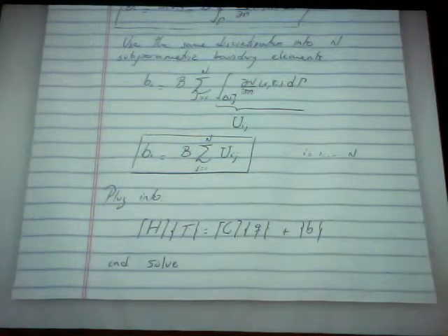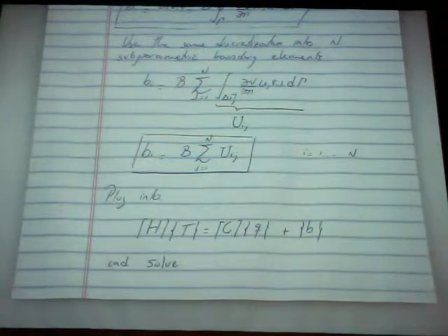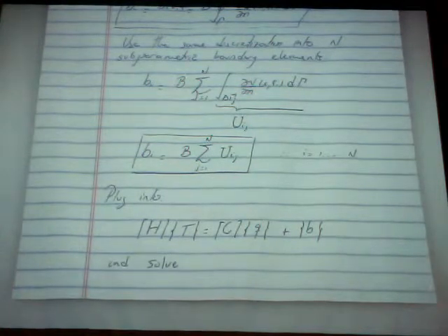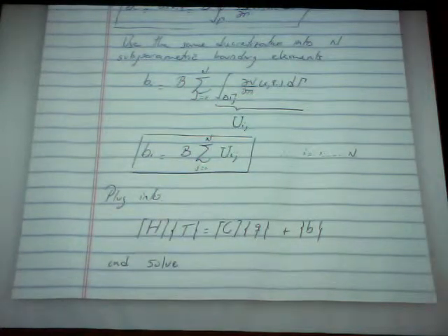Now next Thursday, we're gonna see what we do when the generation is not constant. And that will help us actually cover a much wider range of problems, not only these Poisson-like problems, but other problems in which there's stuff in the equation that we don't know how to handle, and then we can send it over to the right-hand side, treat it as a known quantity, although it's not known, it might be a function of temperature, assume what it is, treat it as a space-dependent generation, solve the problem, and iterate back and forth until we get the right answer.